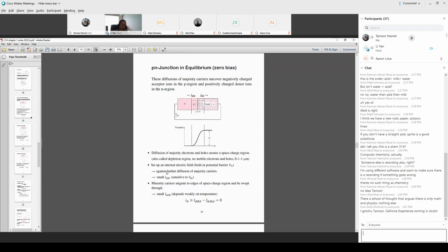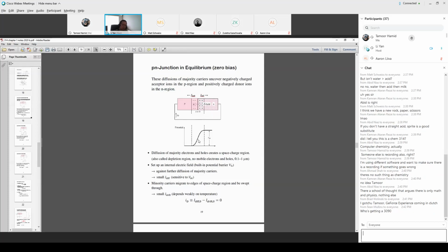Here you talk about electrons. As a substance, you can say that's electrons. But my point is these electrons are coming from the carriers in the N region or from the carriers in the P region. They're different electrons. What we talk about is the diffusion of majority carriers. This potential makes the diffusion of these electrons difficult, but this electric field will pull the electron towards this end.